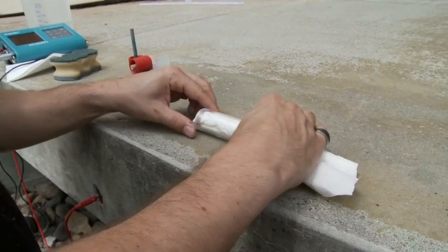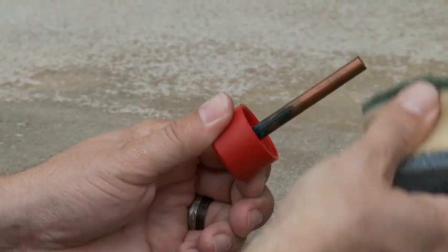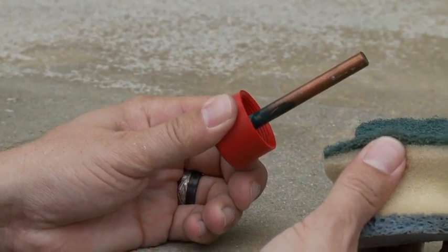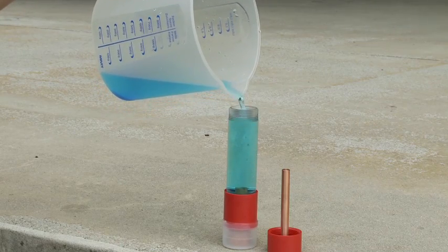To carry out maintenance on the rod electrode, unscrew the 2 caps, wash the tube out with water and carefully clean the inner side of the tube. Clean the copper rod using an emery cloth. Then refill the electrode with the copper sulfate solution.